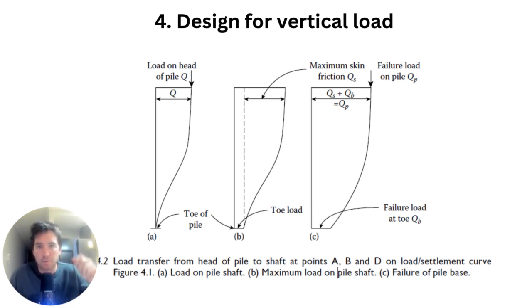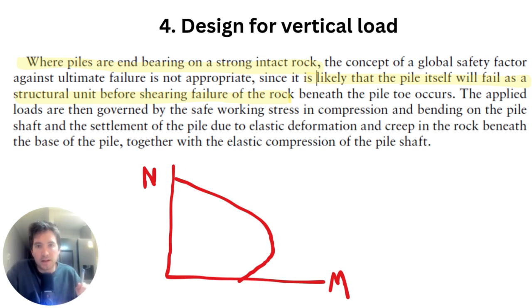So initially the load on the pile, the initial resistance will be the side friction, and then that side friction will get to a point where it's got its maximum capacity, if you will. Then the load will continue as the load increases to the end bearing, and at some point the end bearing will reach its maximum capacity as well. So if your pile is in a rock and you've worked out the maximum bearing capacity, the chances are that pile in the ground, now we've satisfied that we know what the allowable bearing capacities are, and we're not going to exceed that.